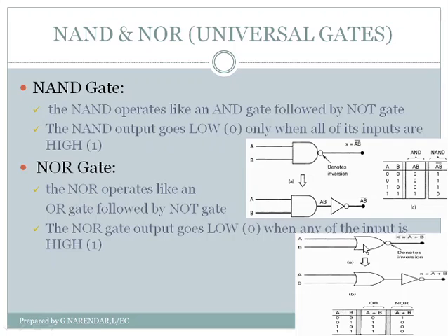That means whatever the result of OR, you need to complement or invert to get the NOR operation. So if the input variables are named A and B, then the output of NOR gate, X, can be written as (A or B) bar, or (A plus B) bar.